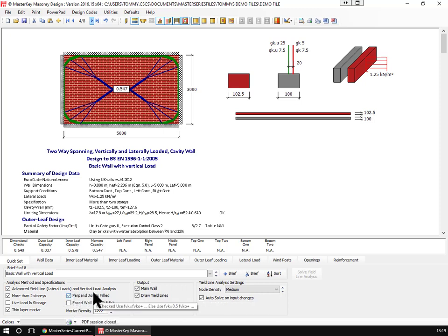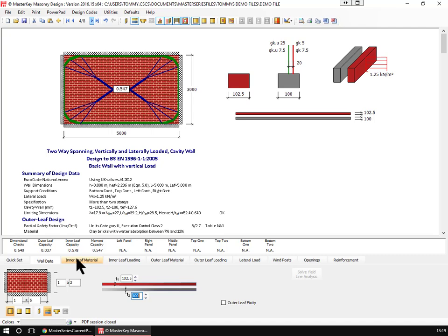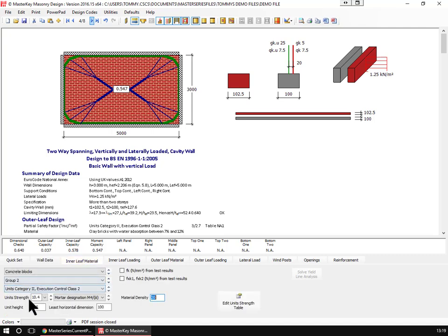Perp end joints are filled because in some cases these wee verticals are not filled. So the perp ends of the blocks are filled, and obviously our mortar designation. So that's what we have here, and obviously we have seen the wall data. Materials, we've seen that, and we have seen that you can specify your fk and fxk, as we used to call it in the British codes, fk, fxk in the